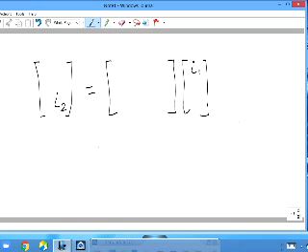Right? It's a little hard to remember the hybrid parameters. But if you remember that I2, or rather IC, is beta times IB in a BJT, then you can remember the hybrid parameters. This is really IC. Okay, if you remember it this way, then you know how to fill it in.